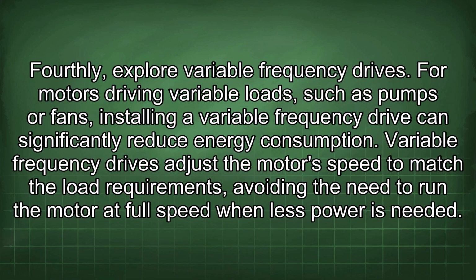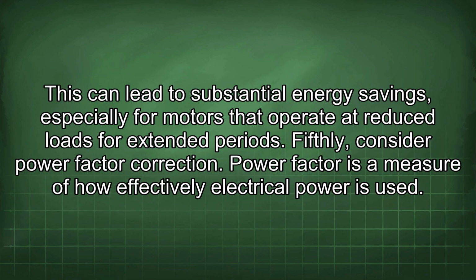Fourthly, explore variable frequency drives. For motors driving variable loads, such as pumps or fans, installing a variable frequency drive can significantly reduce energy consumption. Variable frequency drives adjust the motor's speed to match the load requirements, avoiding the need to run the motor at full speed when less power is needed. This can lead to substantial energy savings, especially for motors that operate at reduced loads for extended periods.